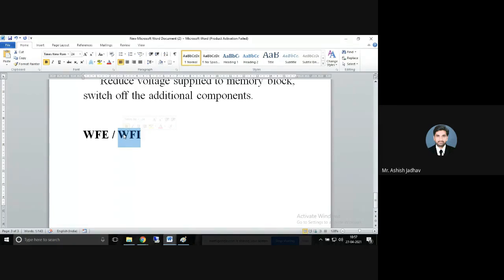Right. So during deep sleep mode, the system clock can be stopped, but the free running clock, or you can say input, could still be running to allow the processor to be woken up by an interrupt. Right. So the two sleep modes are normal sleep and deep sleep. So this is what the Cortex M3 possesses, or Cortex M3 has.